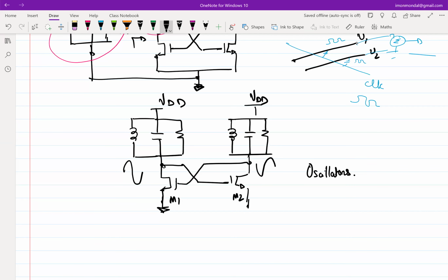Right. If they are ideal, then we can have a charged capacitor. If we first charge the capacitor, then make a tank circuit, if it is ideal, it's going to sustain oscillation at the same amplitude. But because of the non-idealities of the inductors and capacitors, the amplitude dies out because of the positive resistance. Now we have the initialized capacitor, which is already charged, and it is connected to this tank and this cross-coupled pair. Sure. So these nodes, the black dots, will reinforce the initial conditions, because any attempt to change the nodal voltage will be met by negative feedback.